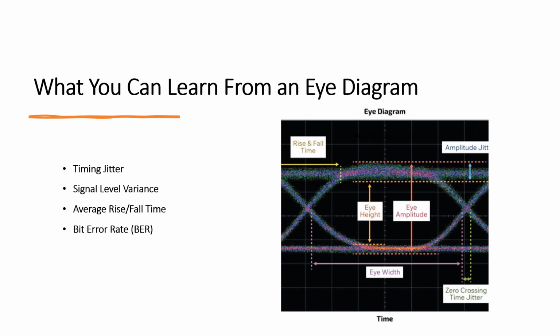In case you are working on a high-speed signal, the bit error rate gives you the data about how many bits are going to get lost during the whole transmission. The ideal bit error rate is 10 raised to the power minus 12 or lower than that. And if you want to reduce the bit error rate, equalization techniques can be used either at the transmitter or at the receiver end.